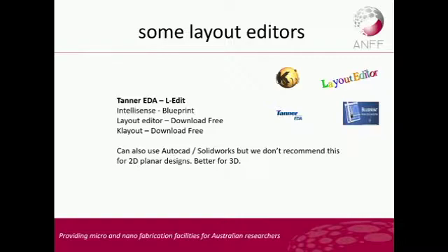So some layout editors: we've got L-Edit, which is my preference, and I think some of my colleagues' preference as well, for doing layout. Blueprint, which is part of IntelliSense, I mentioned. There's also Layout Editor, which is a freebie. You can just download that from the web and use it for doing layouts. And there's one called KLayout, which is another freebie as well, but it can't do circles for some reason.